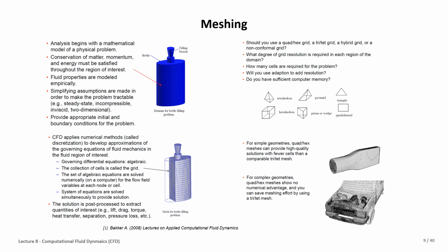Sometimes there is the concept of symmetry. When we have a symmetric problem, we try to reduce the computing. For the symmetric case, we divide the domain of the problem and solve, for example, half of the problem or sometimes a quarter of the problem, and then extend it to the whole domain of the problem. There are different techniques that need to be used in CFD to be able to run the simulation and reduce the computer memory and also the computing time.